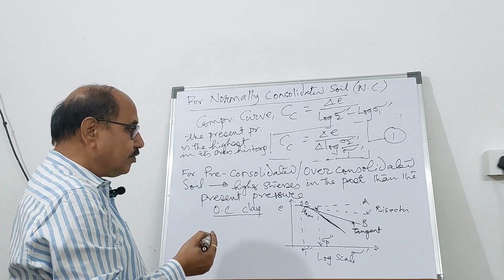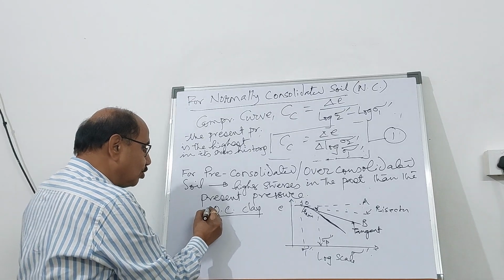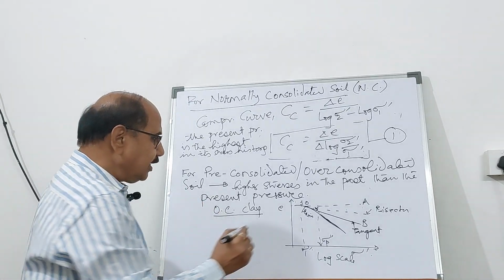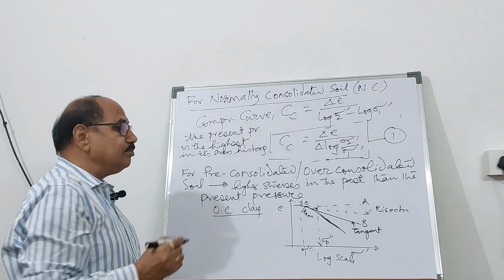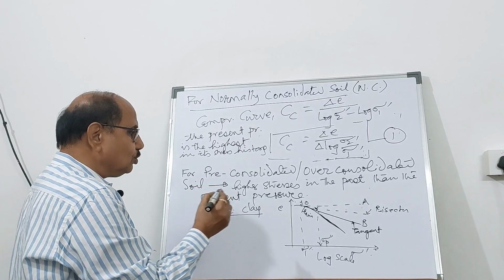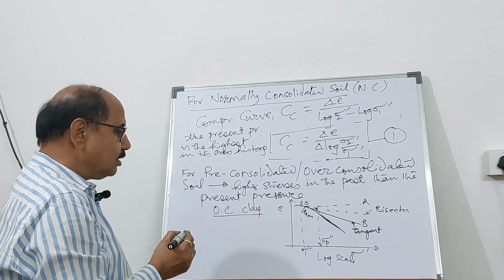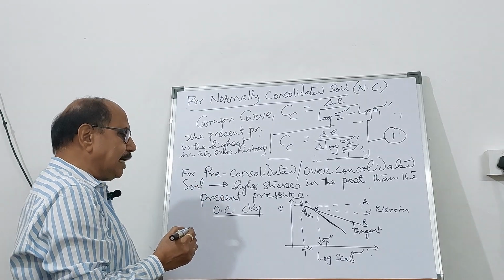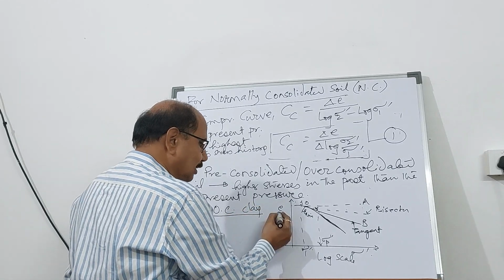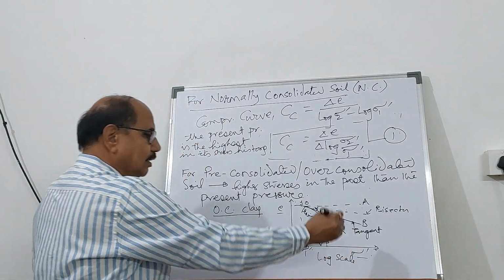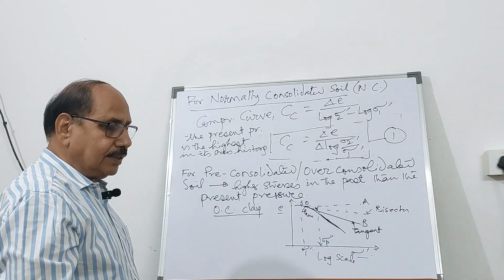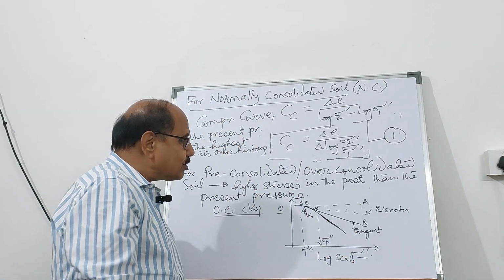Therefore, it will behave like over consolidated clay. It is, and to find out this is very, very important. So you need to carry out the consolidation test, and you will have to plot the void ratio versus the effective pressure over the soil mass.